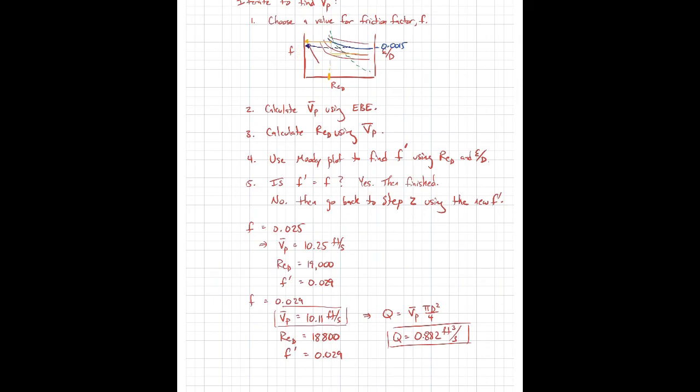That's a very reasonable first guess, and it seemed to work pretty well. In fact, I only had to do 2 iterations, and I found my answer. So use a reasonable first guess. Don't use a friction factor of 1,000,000 or 1 times 10 to the minus 8 as your initial first guess. That's a terrible first guess. Choose something that's in the ballpark of what the answer will likely be, and that'll really help you out.